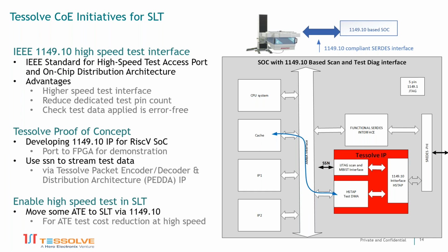Gotcha. Okay, thanks. So you're right, it's a very good question, and I don't think there's a quick answer. It's all about analysis of yields and test times, etc. But you could potentially see that if you can get 99.5% yield from your ATE, but you move half the tests into the SLT and finish it all off there, your cost equation might come out positive by moving those tests.